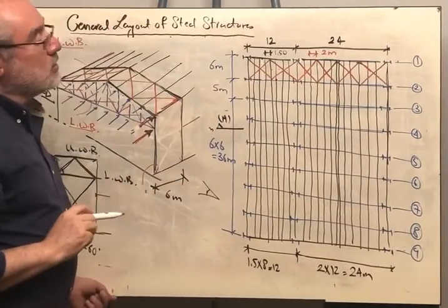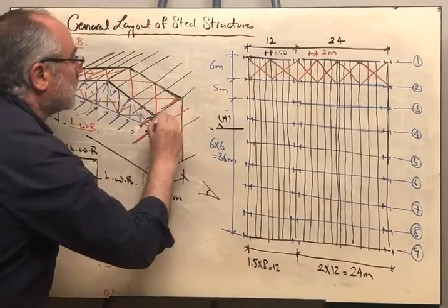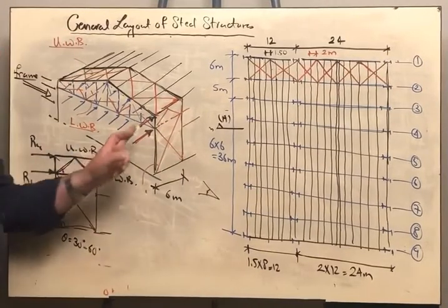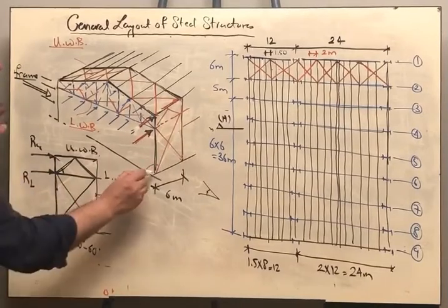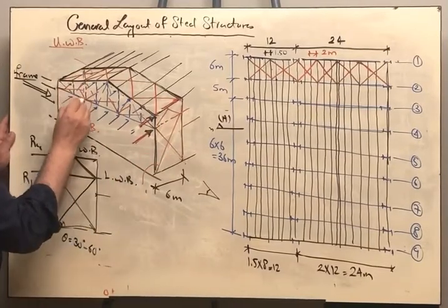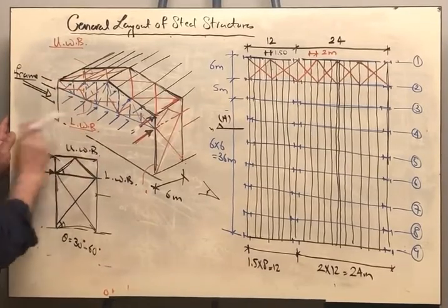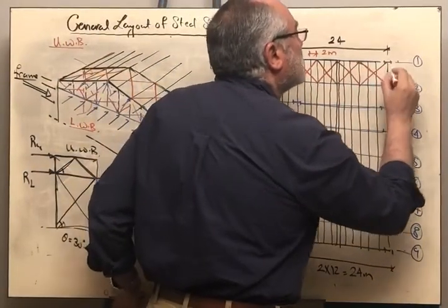Top question. Where would be the vertical bracing? The vertical bracing, as you can see here in this example, as we solved it together, is established between the 2 columns. I should have vertical bracing here and vertical bracing between the other 2 columns there. I don't have any vertical bracing in the middle. Now I am having a column here and a column there.